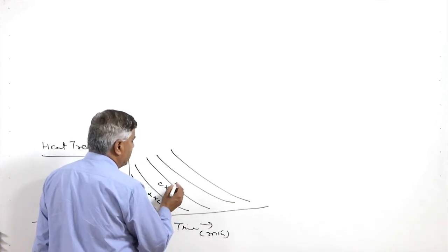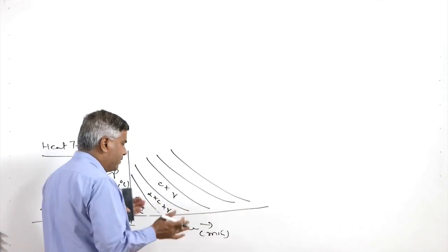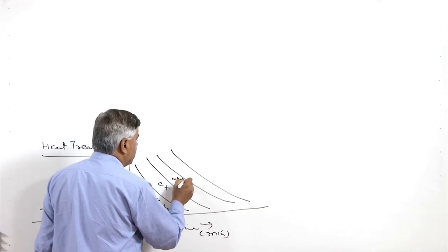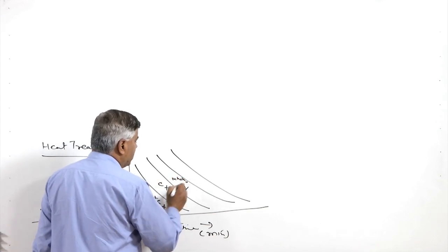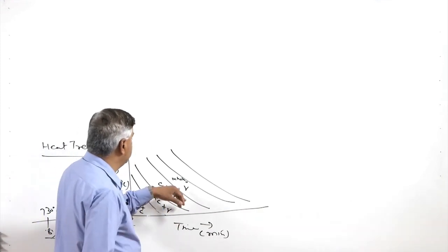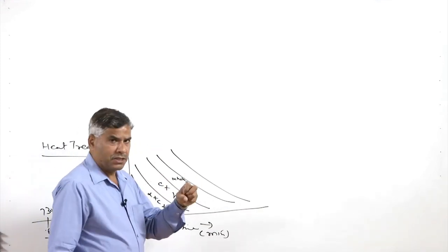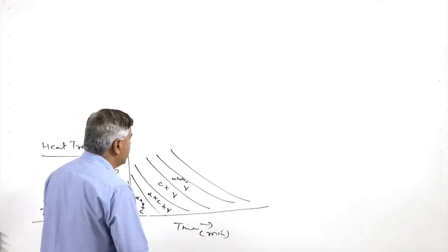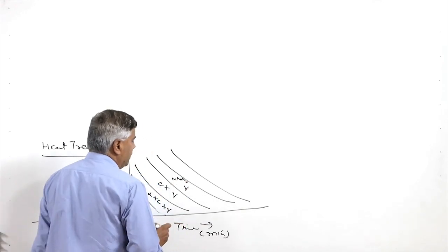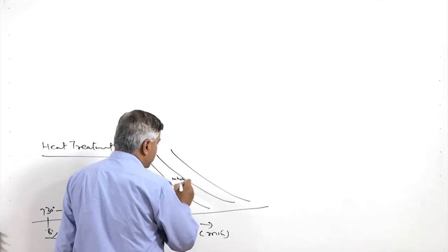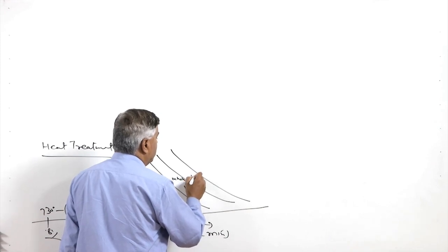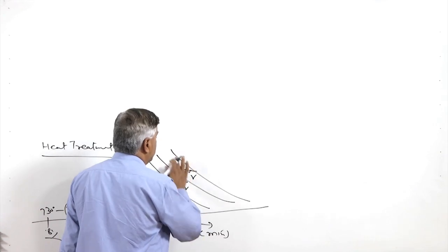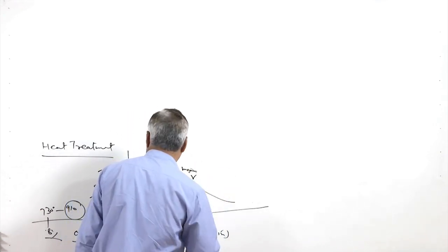Now, the carbides will decompose and they will form inhomogeneous composition of the austenite, because of the higher concentration of the alloying elements and the carbon at the location where these carbides were. So, it will be leading to the presence of inhomogeneous carbon content and alloying concentration. Further, if we give more exposure, then it will have the homogeneous austenite. So, these are the kind of zones which are formed.